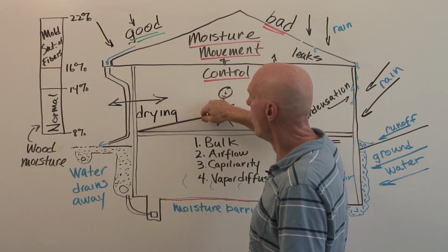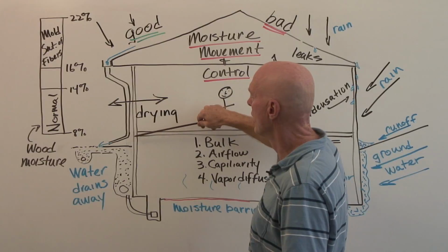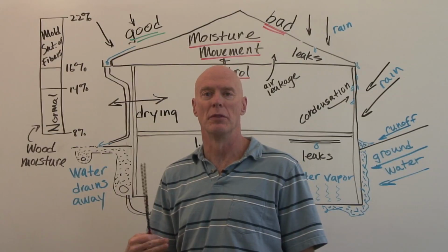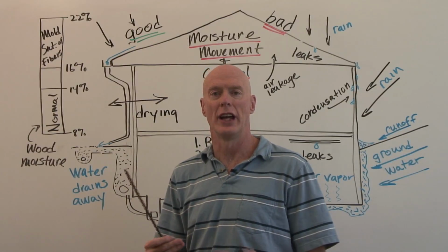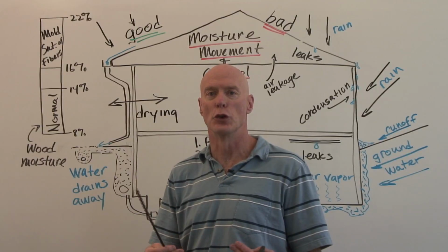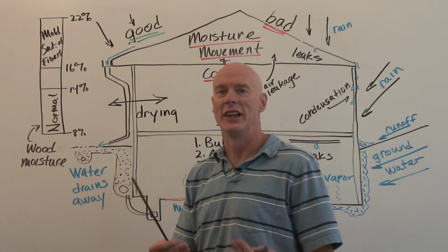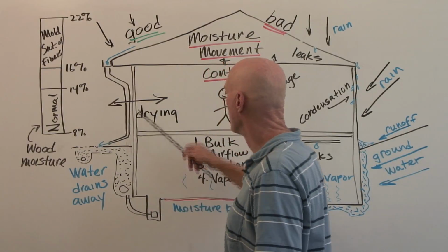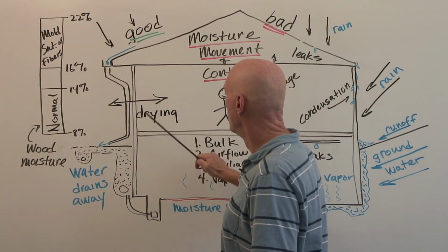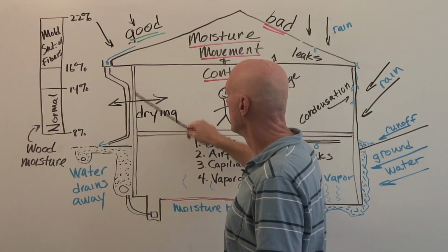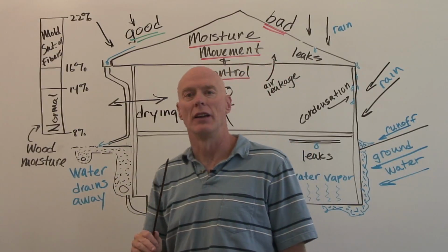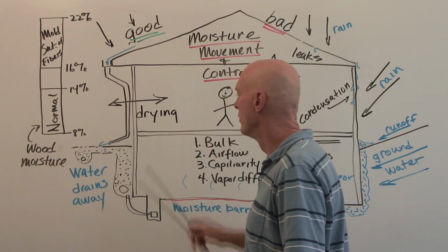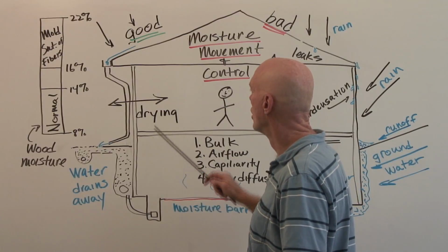You've got vinyl wallpaper, you've got polyethylene vapor barriers. On the outside, steel siding, aluminum siding, vinyl siding are all pretty much a vapor barrier, although the steel siding and the vinyl siding have drains in them for when they get condensation on the back of the siding, so the moisture can drain out of the siding. But we have to be careful about putting vapor barriers in a wall. The reason is we don't want the moisture to get trapped in the wall. But there are bigger problems that we need to solve here.